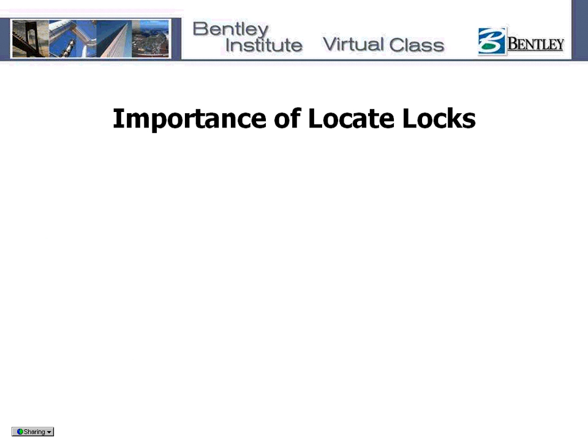Before I go any further, I want to emphasize the importance of locate locks with EditSurfaceCommands. Many of the EditSurfaceCommands work with the locate lock. This helps the tools to locate either a feature or a graphical element. Locate lock will cause some of the commands to change what they prompt the user for.